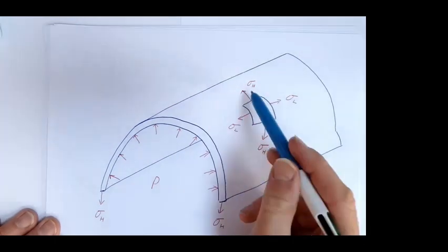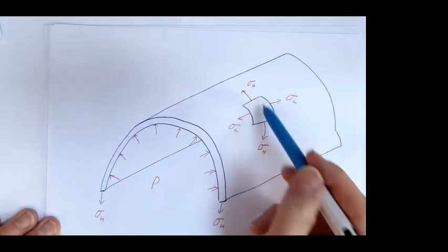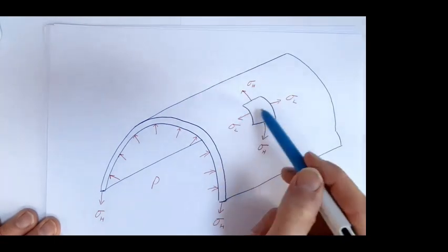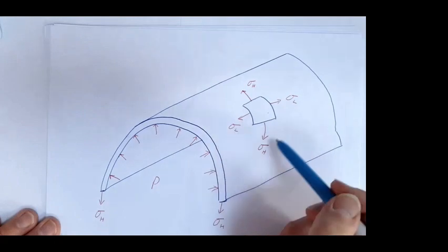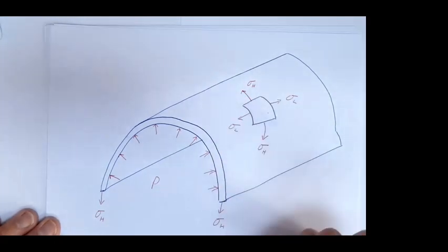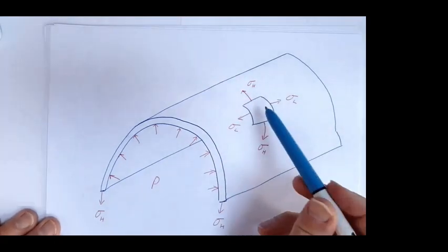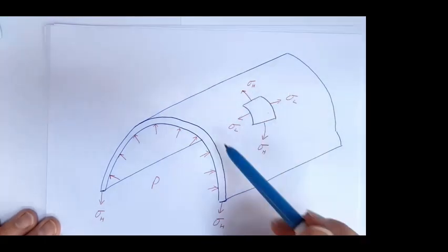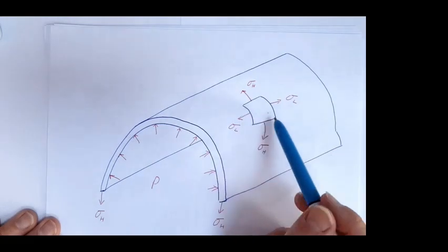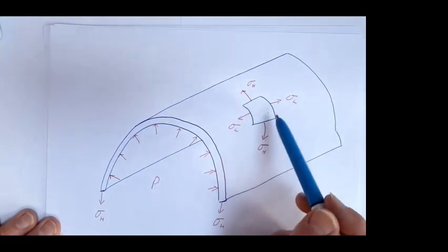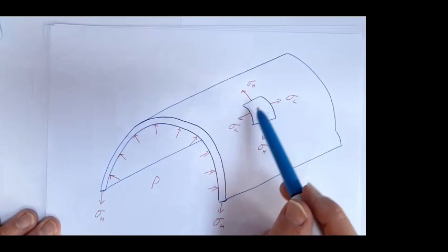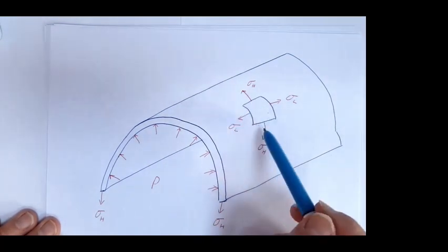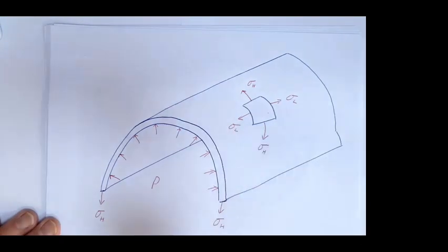So we're just going to consider these two stresses, the hoop stresses and the longitudinal stresses, which are acting at 90 degrees to each other. Hopefully that looks familiar to you. We've talked about that when we've been talking about complex stress, and I've been saying this is sigma x and this is sigma y, or vice versa. Again, we'll be able to work out the stress on any plane of interest and also the principal stresses. Okay, we've got much the same scenario here. We've got a piece of material with two mutually perpendicular stresses, the hoop stress and the longitudinal stress.